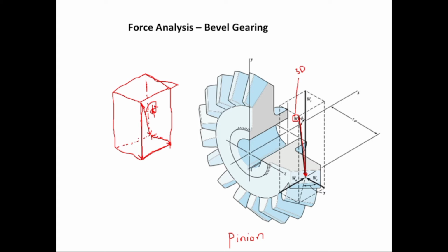So if we sum up these rectangular components by the head to tail rule, it will give us again the same force W. Another way is to start from the tail of the force W, move down in the y direction to give us the y component, and then when we get to the bottom face, meet this y component with the actual force like this. The heights of all the faces are the same, so these two lines are equal to each other. So for better understanding, let's draw one component like this on the corner of the back faces.